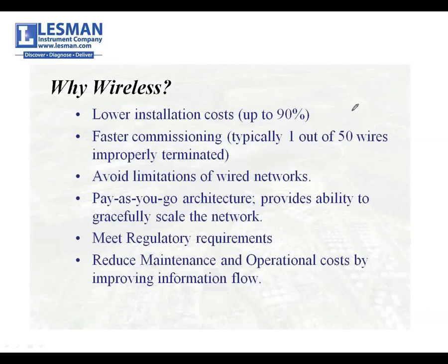Okay? So why wireless? It's certainly about lowering installation costs. We've found it can be the difference between a project going through and a project getting mothballed because the impact of pulling wires can be so tremendous on the budget. Faster commissioning. This stuff is very easy to set up. Some of it is a little bit more complex. We'll set it up for you. It is all non-volatile memory, so if you turn it off, it does remember what it's supposed to do.